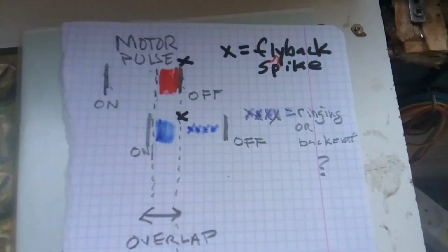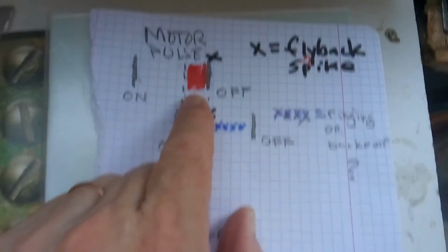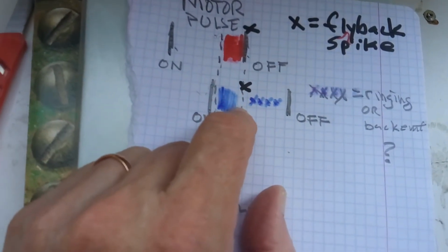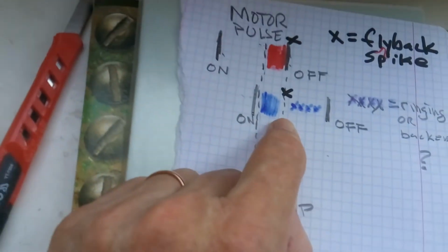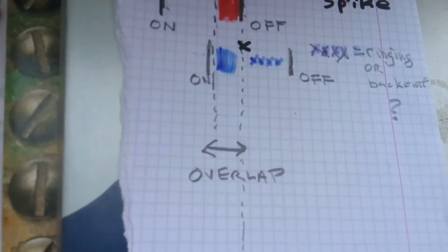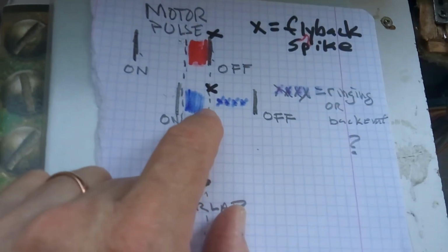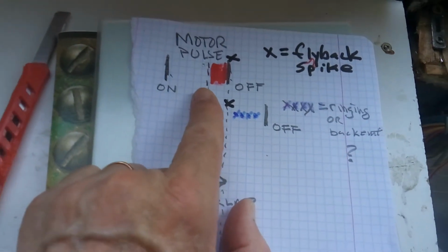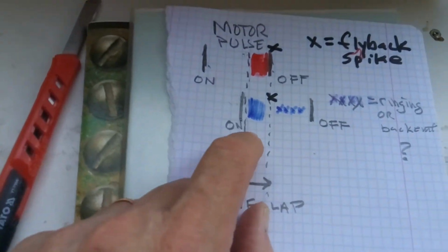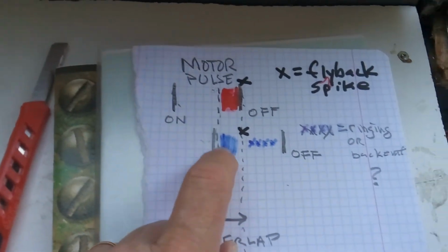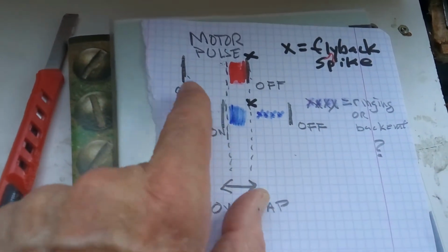And the same thing if you fill up very large capacitors. By very large, I mean things over 100 UF. You're going to see every time it fills that capacitor after a discharge, it's going to cause the draw to go up. So this makes it so the draw does not go up when you do it like this.